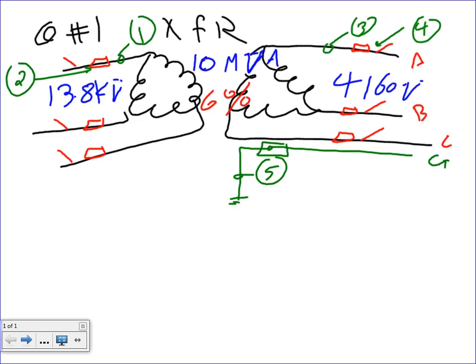If you guys do me a favor, I'm going to have the short circuit calculation too in a second, but let's go to Article 450 and do the sizing. Yesterday I told you which table we're going to go to. Since primary and secondary are higher than 600 volts, we're going to go to the table for over 600 volts. All right, let's go size the conductors.